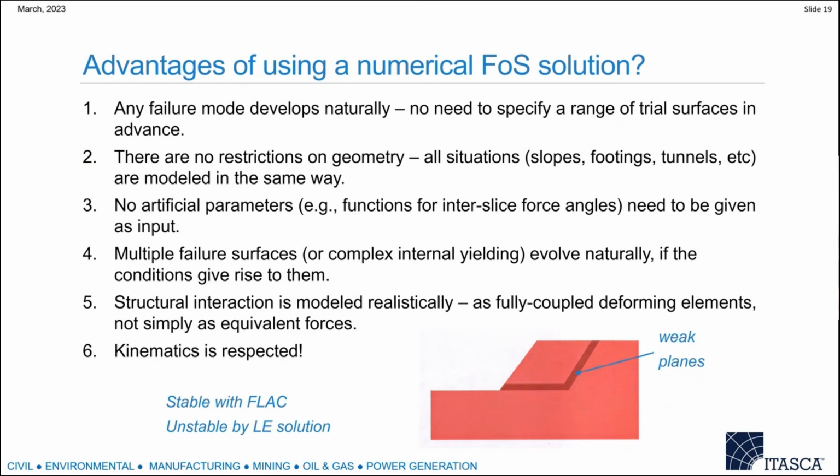Number two, there is no restriction on geometry. So all situations, slopes, footings, tunnels, etc. are modeled in the same way. Number three, no artificial parameters need to be given as input. For example, the functions between interslices, what force angle, horizontal or along the slope angle or whatever. So we don't need to assume this slice force angle.